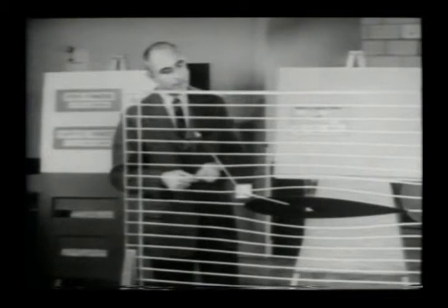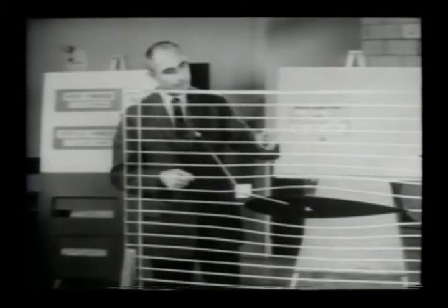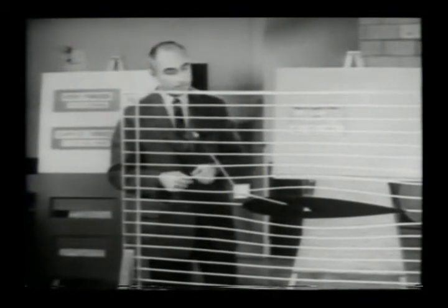Incidentally, the instantaneous direction of the particle motion need not coincide with the direction of the acceleration vector, nor for that matter need it coincide with the direction of either of the two force vectors. Here is a sketch showing the parallelogram of forces, and here is Newton's equation. Net pressure force plus net viscous force equals the product of mass with acceleration. For short, this mass acceleration product is often called the inertial force.